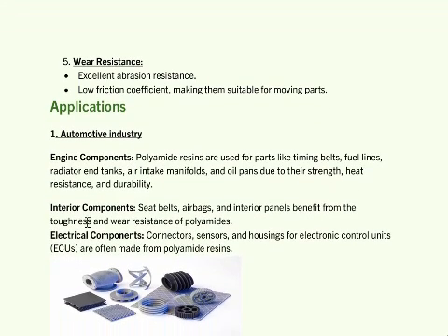Moving toward the applications, in the automotive industry, engine components, polyamide resins are used for parts like timing belts, fuel lines, radiator end tanks, air intake manifolds, and oil pans due to their strength, heat resistance, and durability.